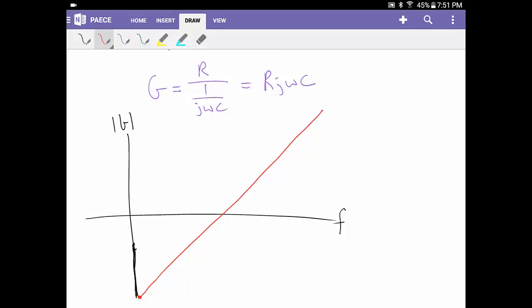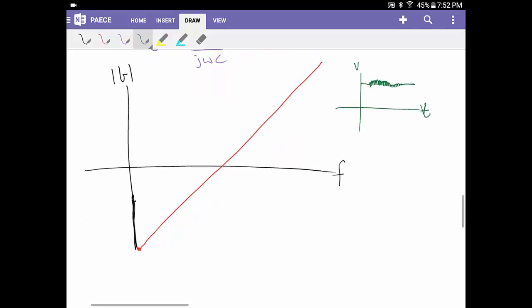This is, again, problematic, especially when designing circuits. So from a mechanical engineering standpoint, if anything's near a motor, you're going to have a lot of high frequency noise. And what this circuit does is, you may say, great, I'm knocking out all the low frequency noise I don't care about. But let's say that you have a noise spike. You may be dealing with a circuit where here's time and here's voltage, and you may be trying to read some DC level, but your DC level has all this little high frequency jitter on it. The issue is, when it goes through the circuit, that high frequency jitter is high frequency, which means that it's going to have its amplitude magnified by quite a lot. So again, we have this undesirable characteristic of our infinite gain and infinite problems.